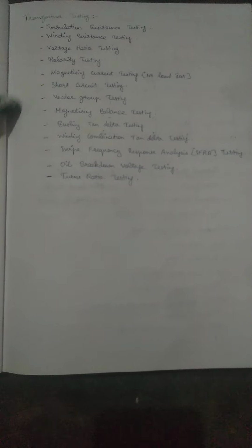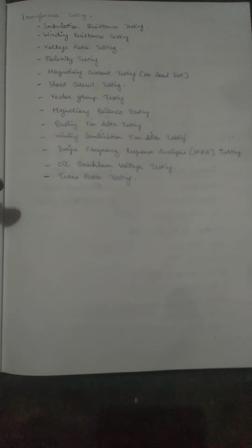Also, we mostly need to give preference to doing the AC test first for our transformer. Then after finishing the AC test, we go with the DC test, because the AC test is normal, like a low voltage charging, but the DC test can get affected with our body itself.